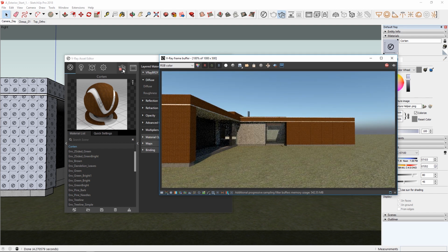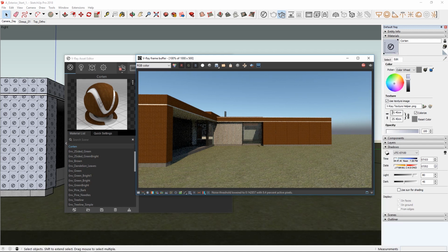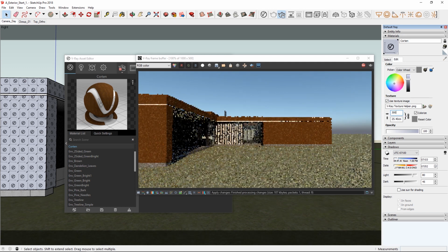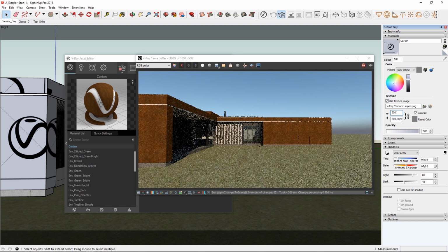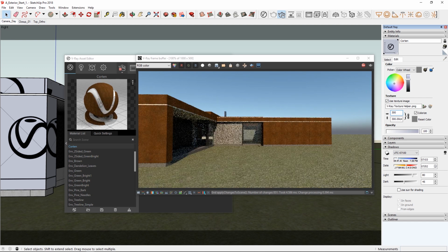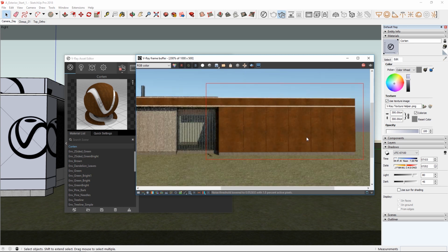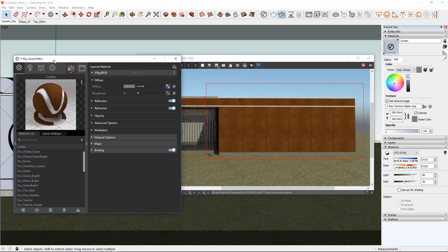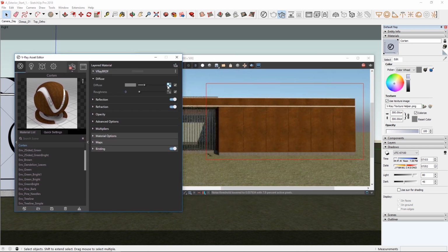The pattern on the panels seemed too small, so to fix the scale of the texture, just like I did with the grass, I'll adjust the size from the SketchUp's material panel. I'll try 300, which I think should be enough. Okay, that looks much better now, but it looks all very uniform. I'll fix that by adjusting each of the bitmaps.